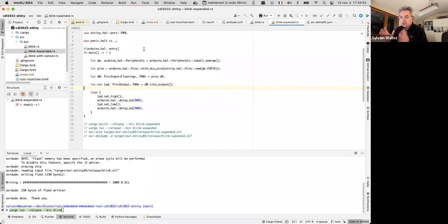They are just registers that are mapped onto memory. And in order to control those pins, you have to set a bit to 0 or 1 in a register. So it's all driven by memory. The hardware abstraction layer is a wrapper around those registers that gives us more semantic and meaningful methods.